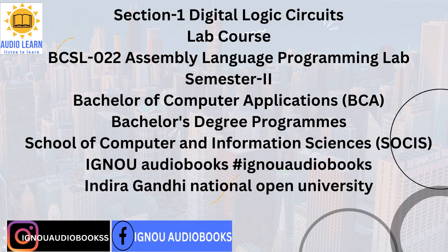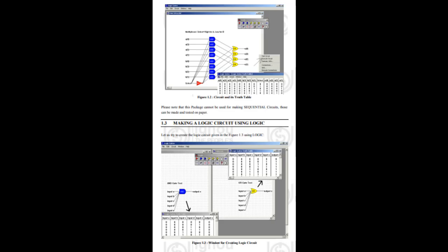On execution, a simple screen appears having a two-menu option, File and Help. Select the New Project option of the File menu to get the project window. Build logic gate constructions using a grid on the screen. It also includes a gate and connection toolbar. Please refer to Figure 1.1.